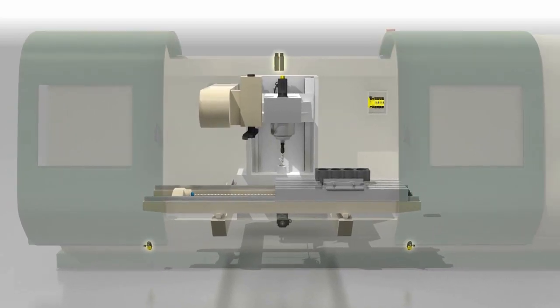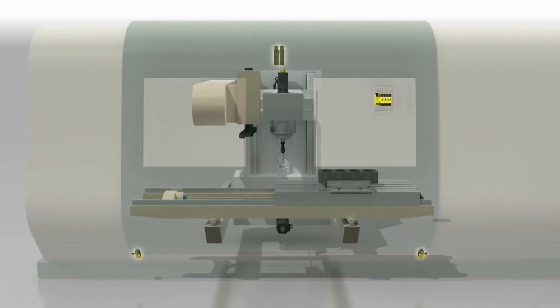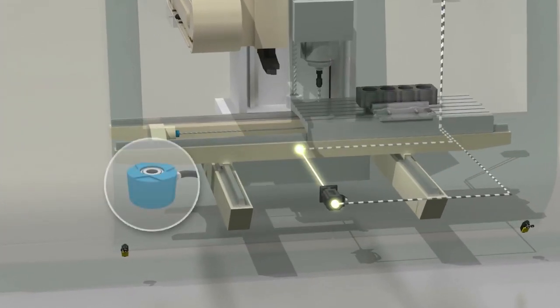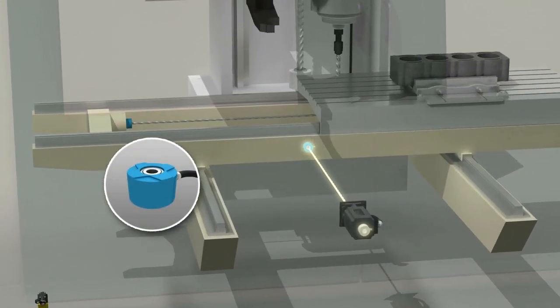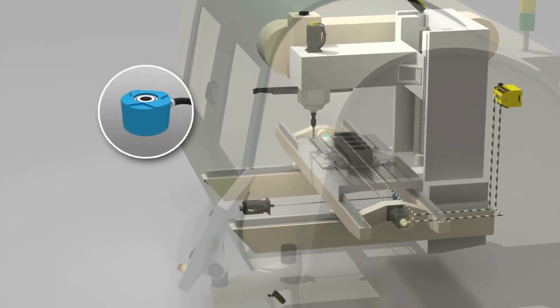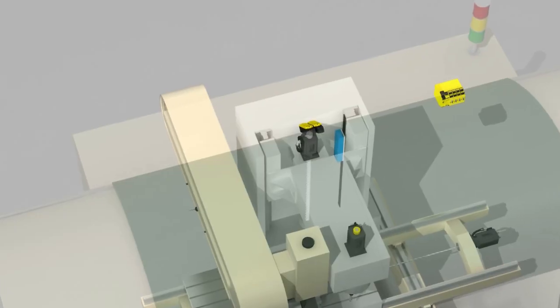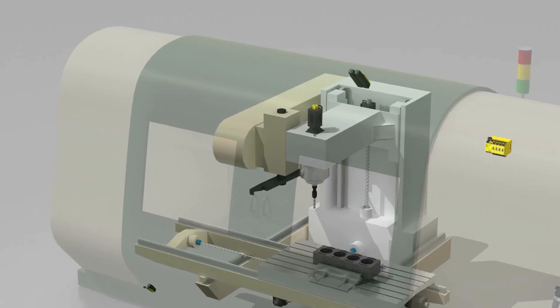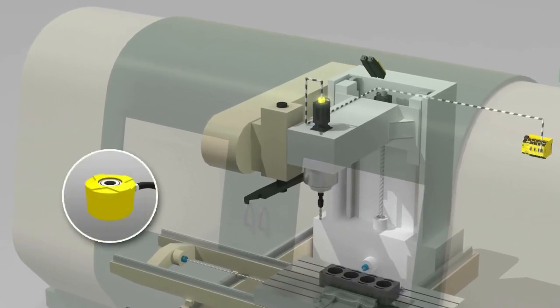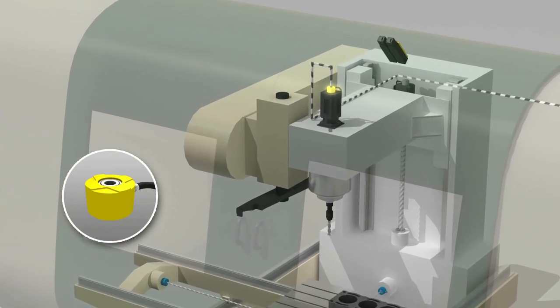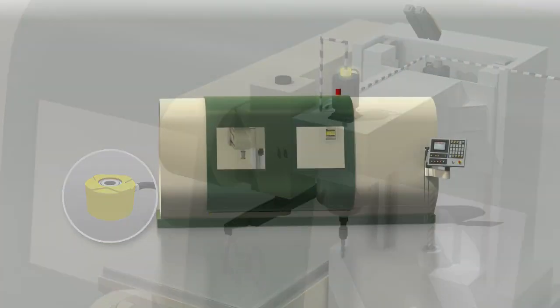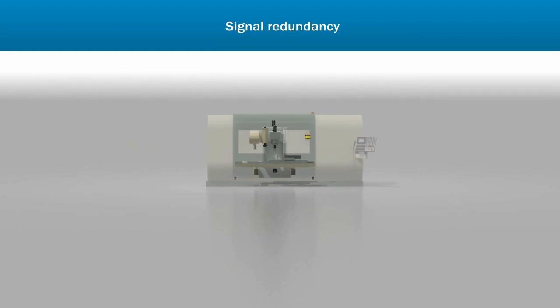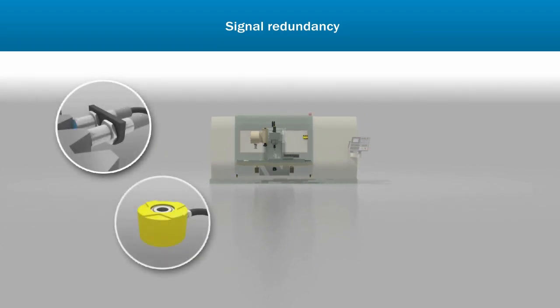Various sensors are used to monitor the motion sequences in the machine. They include motor feedback with an additional rotary encoder or an additional linear encoder, as well as safe motor feedback. This is used for signal acquisition at the axis. Proximity sensors are another option. They capture redundant signals from the axis that are being monitored in the drive monitor.